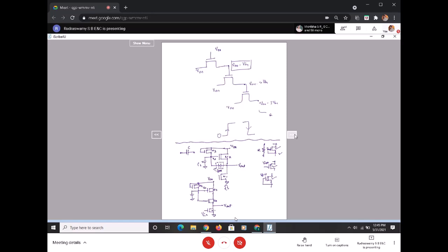So what I'll try to do is short these two terminals, the source and the drain terminals. I will short them, and it becomes a single terminal. This is my gate. Now this particular M4 is acting as what now? What is this acting as? I have one gate terminal, and then there is an NMOS transistor. What is there as a gate? Oxide, right? Yes, I have a gate oxide.